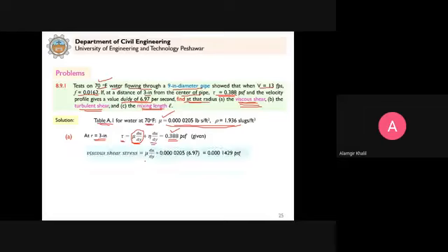In this case it is easy, because mu comes from the table, you put this mu value here, and du/dy is given as 6.97. So you calculate the viscous shear stress. You can see here, as I already stated, it is a very small value, 0.000 something. Although we used this equation to calculate the total shear stress for turbulent flow, the viscous shear stress has a much smaller value as compared to the turbulent shear stress. But anyhow, for accurate determination, we have to consider this.